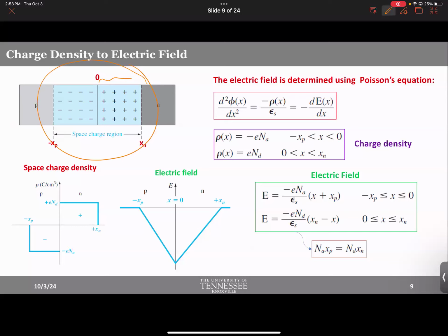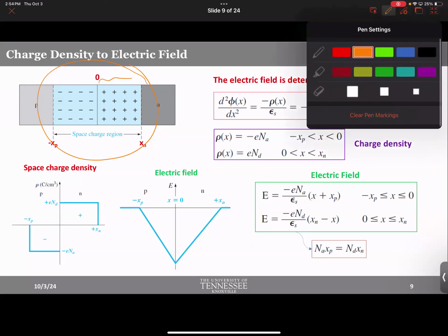I mean, if I told you that the solar cell efficiency, will it be 15% or 20% or 22%? Depends on the design. I'm saying this because you can control the space charge region, by the way. Figuring out how to best control the space charge region, that determines your efficiency. Would you now be interested? Right? And this xn plus xp, this simple line, will actually help you design. You have to reduce one of them and increase the other one. Now you see. Okay, the simple equation leads to an entire direction in research, solar cell optimization.